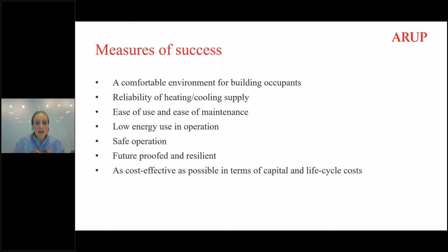end of life. I wanted to highlight, however, that while we're going through this process, what are we really trying to achieve? We're trying to achieve a successful heat pump installation, which we've defined as something that reliably delivers the heating and cooling loads to the building occupants and clients, that's easy to use and easy to maintain, low energy use in operation, safe to operate, future-proofed and resilient, cost-effective from a whole life perspective, covering capital, operational, maintenance and replacement cost, and also carbon efficient from a whole life perspective.